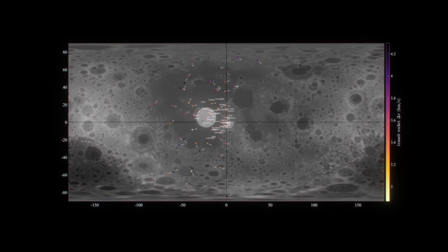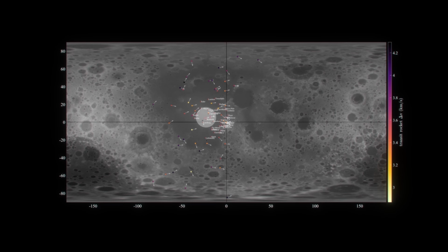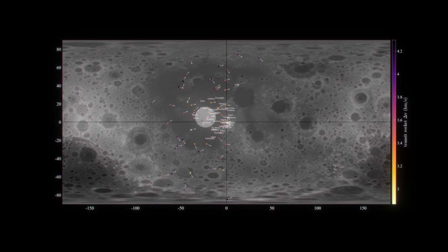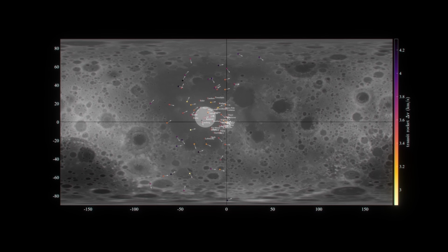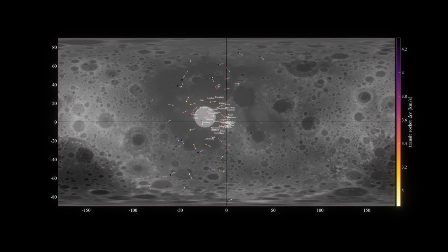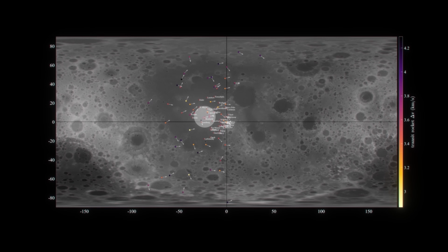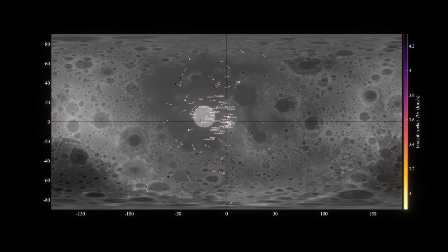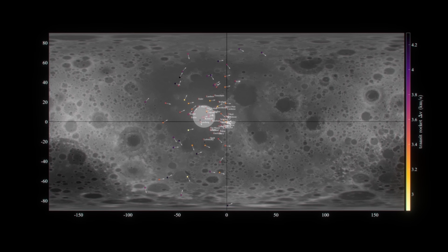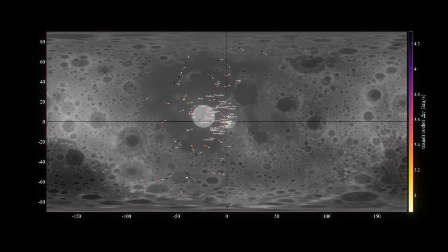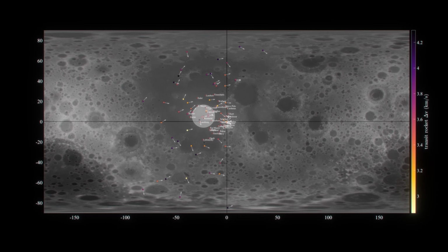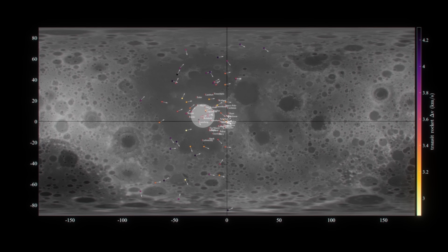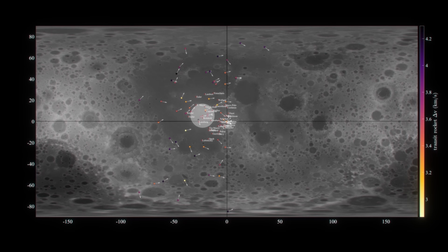Well, there is one recognizable pattern, and that is that the lunar poles are unfavorable places to put a mass driver, because the vehicle has to always fight larger inclination changes when leaving the lunar sphere of influence. But besides that, a lot of locations across the lunar west perform similarly in Delta V. So instead of getting one obvious answer, we got a rough region. The problem though is that for the next phase, which is the bulk of the work, we need one actual point. So we need to consider other factors of merit to determine placement outside of raw Delta V figures.